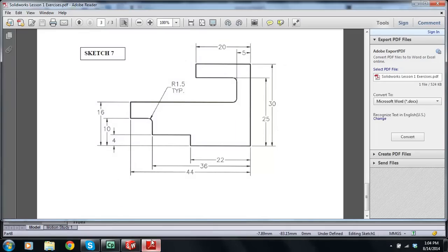So where is a good point on this sketch to put the origin? Where do you want the origin to be? My feeling is I just want to put it right here, right at the bottom right hand corner. Okay, and then what's the plan of action? I don't know what this thing looks like. It looks like some sort of an iron, to be quite honest with you, with all these little curves. We're going to draw everything in, and we're going to add in these fillets last.